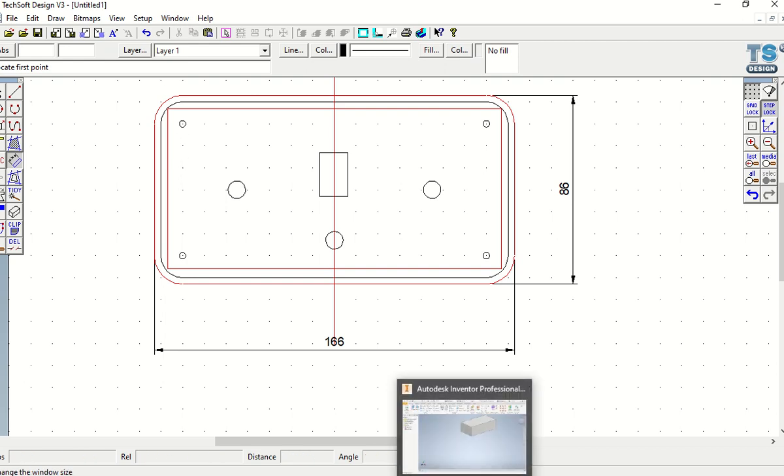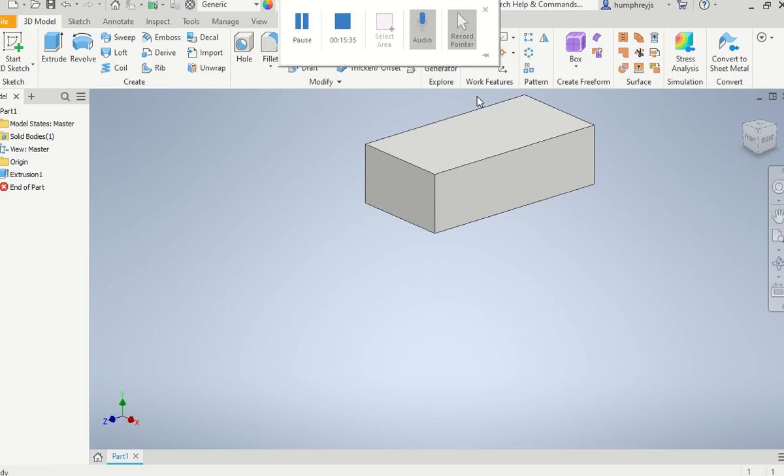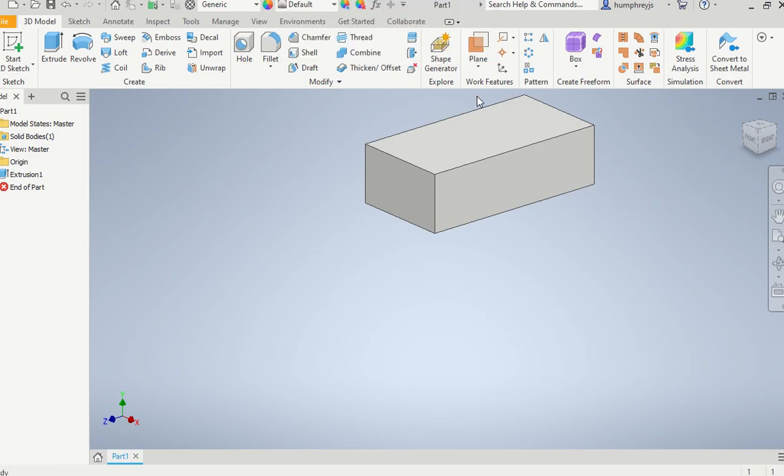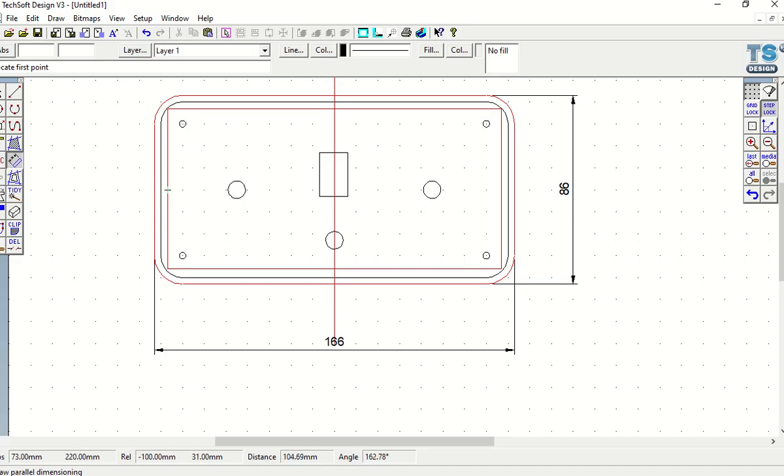Right, so next up, I now need to think about a couple of things. I need to cut away a hole going through the middle. The hole going through the middle is this section here between that point of the red rectangle and that point of the red rectangle. So it's going to be 6 millimeters shorter here and 6 millimeters shorter there. So it's going to be 74 by, and of course the same here, 154. It's going to be 6 in from each corner.